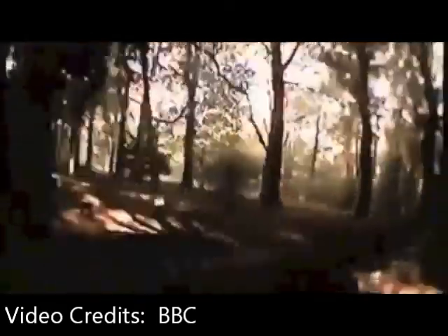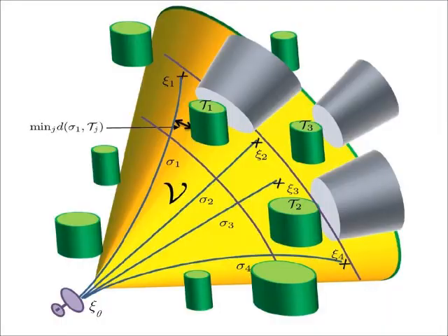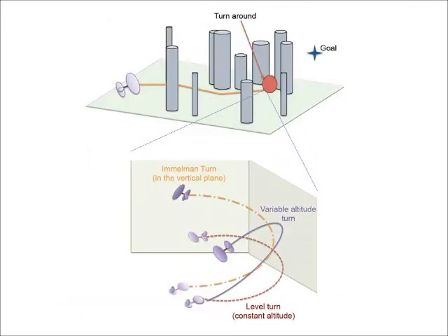First, the algorithms have to identify collision-free paths and the control inputs required to fly them in a very short span of time. Second, the computation of the control inputs has to duly accommodate the nonlinear dynamics which govern the motion of an airplane. In addition, the motion planner should be equipped with maneuvers which can allow the aircraft to backtrack from dense, impenetrable pockets of obstacles.